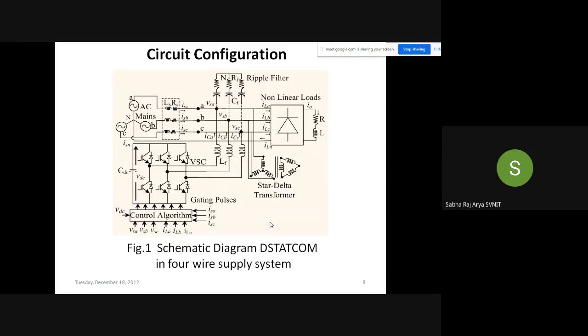Also, if we are going to use a sequential processor, like a microcontroller, then the operation is sequential, and if we are going to use an FPGA based processor, the operation is parallel. In the case of a sequential processor, we cannot say our system responds very fast, because people already know that the system performs by sequential operation. But in the case of an FPGA based processor, the operation is parallel, and in that case we can say our system is fast.